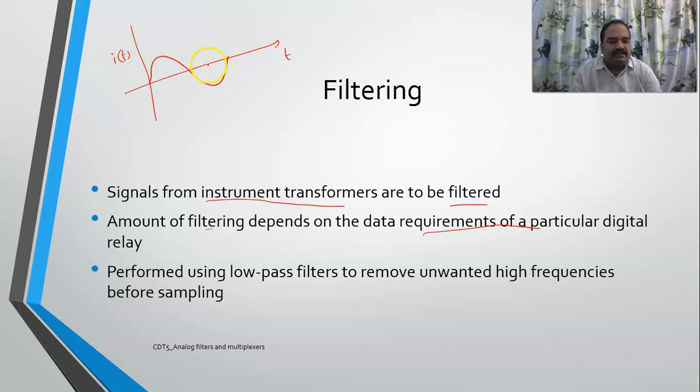let us suppose this is a current signal and it has a frequency of 50 Hz. That's fine. Now let us suppose there is any disturbance happening in the system, then there is a chance the current may increase, right? See, the current magnitude, this is a faulty signal, let us suppose. The current magnitude has increased, but if you carefully see, it is still only a power frequency signal, just having a different magnitude. So this is okay.